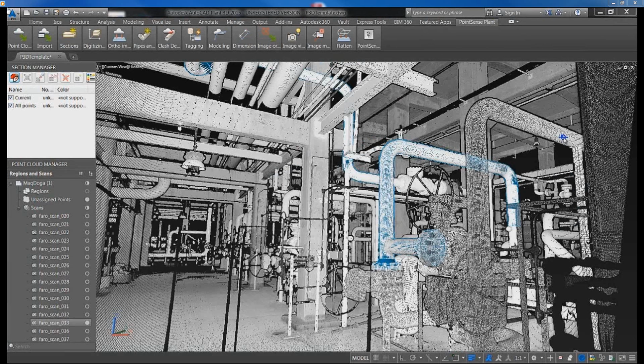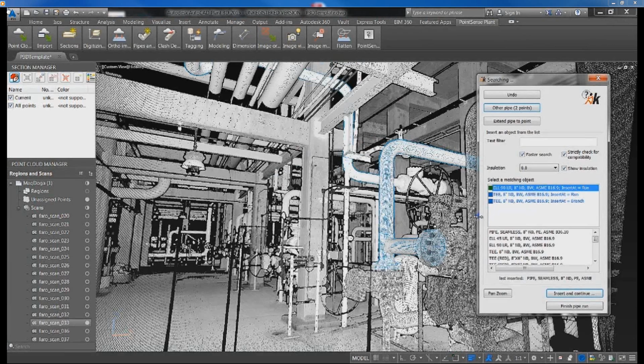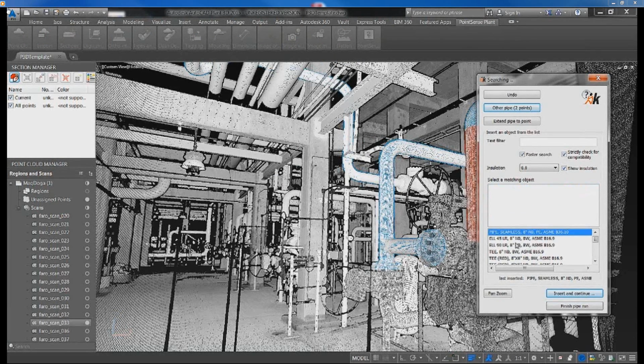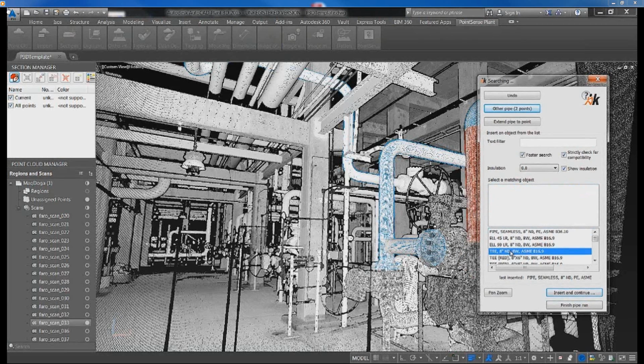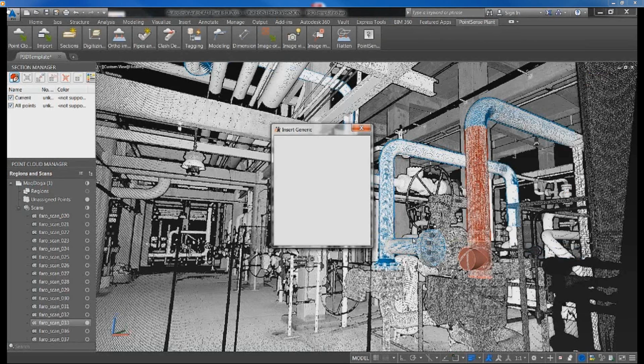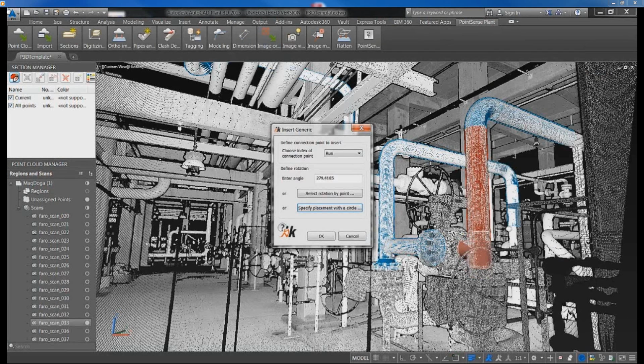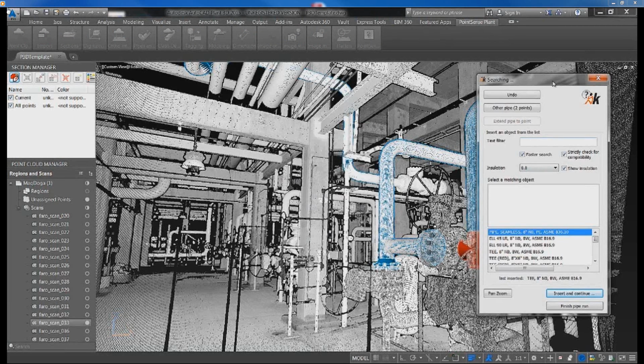And they'll warp in a small amount, but still, it's enough of an amount that your design package will either give you water drops or it won't even see the fittings as being connected. I'm sure everyone here has generated an isometric where each fitting came out on its own isometric. It's not fun. It's kind of a nightmare. But at this point, all I have to do is run apply constraints. It heals the line, and then we'll be ready to take this into Plant 3D.